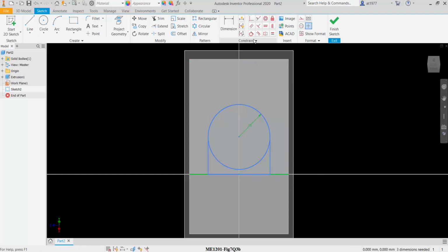Alright. The next step is to constrain the lines and also the circle. So ensure that this line seems like already coincident with this. What we need to do is ensure that is the point. Alright. Okay, notice the guiding line is horizontal. Make sure this line is horizontal. Okay, I want the midpoint of this line to be the same as the part origin.